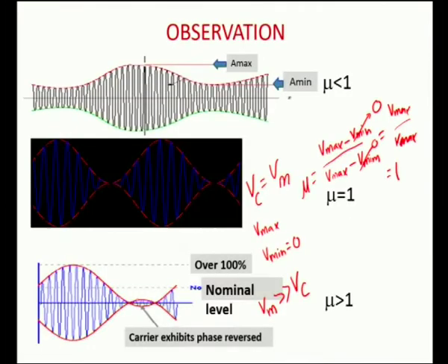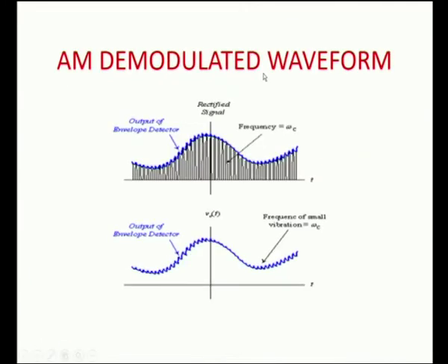This form we have already seen. We will be giving these 3 types of waveforms, and we are going to pick up the envelope of these waveforms using the demodulation process. This being the input to the diode circuit, the output seen at the CRO will be like this. There will be small ripples, but more importantly the message signal will be reconstructed after the diode demodulator. This is also called an envelope detector.